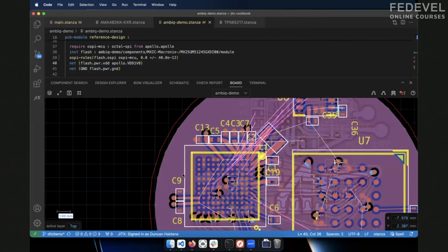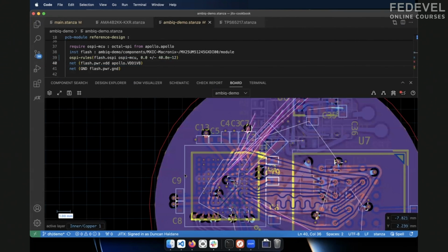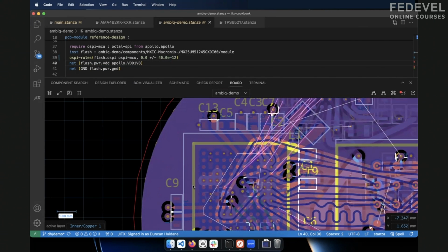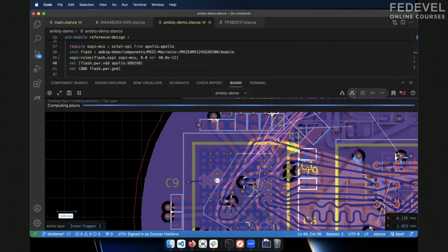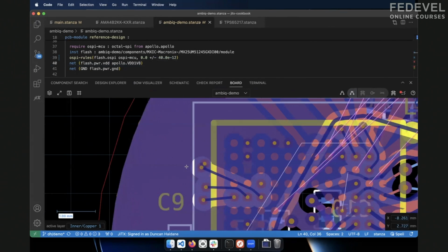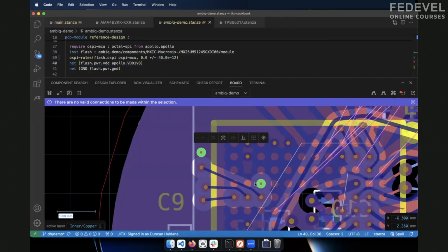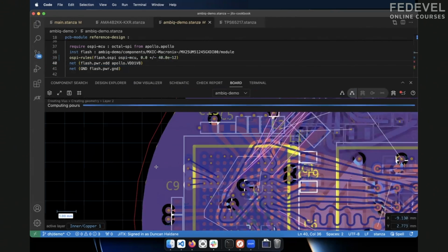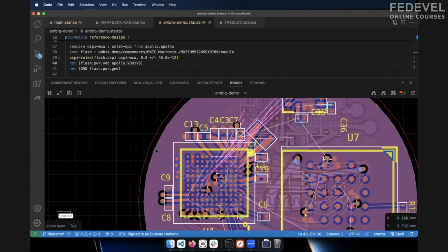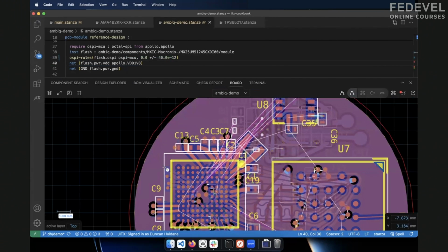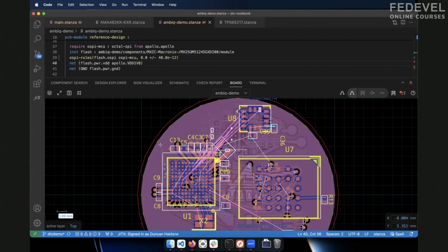And now to route out, I need to break out to top micro vias again, right? All right, so let me just do that. Via type still the same. And get my signals out here. Oop, missed that one. Okay. And now should be able to route, right? Yeah, okay, so this one wants to go that way, which is a bit awkward.